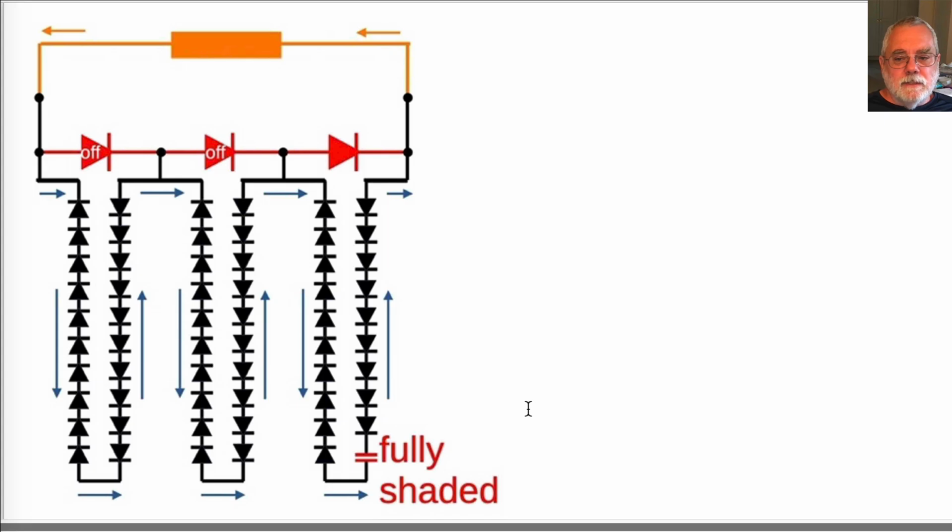The string inverter system should source power if most of the panels are sourcing power. However, if different panels are partially shaded to different amounts, I would think that microinverters and DC power optimizers should deliver more power to the load than a simple string inverter. They will operate each panel near its maximum power point for the given illumination.